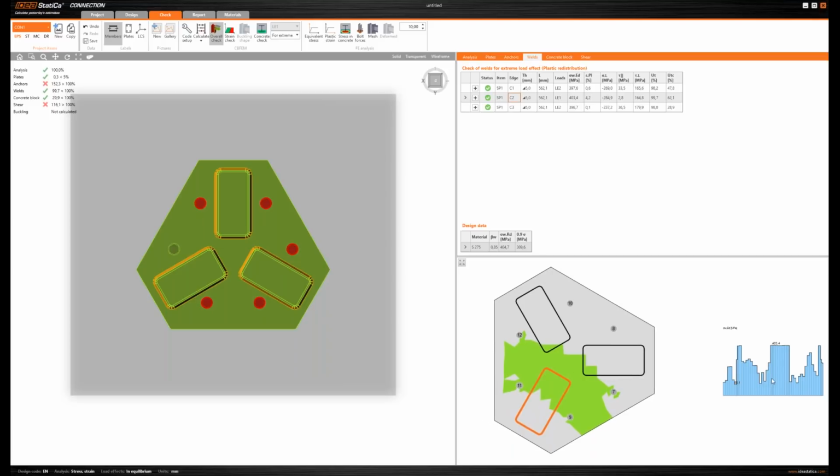Next to this view, I can see an unfolded diagram of weld stresses, and of course we can see the maximum, the resistance, the maximum applied stress. We can see the maximum plastic strain and the stress components that are required from the code for the calculation.